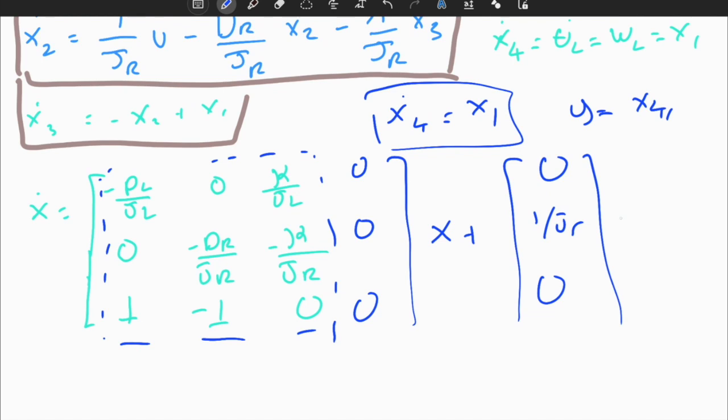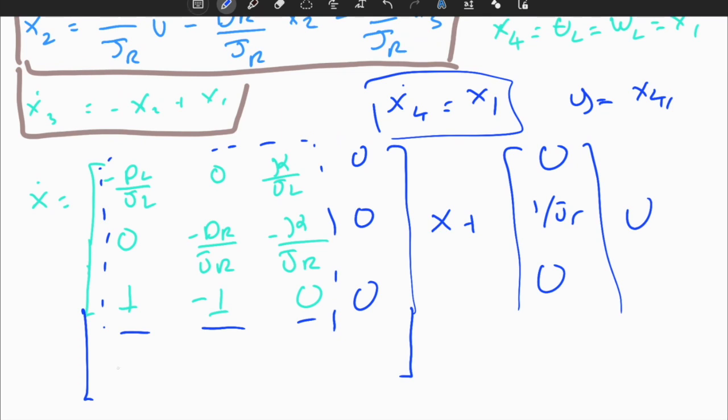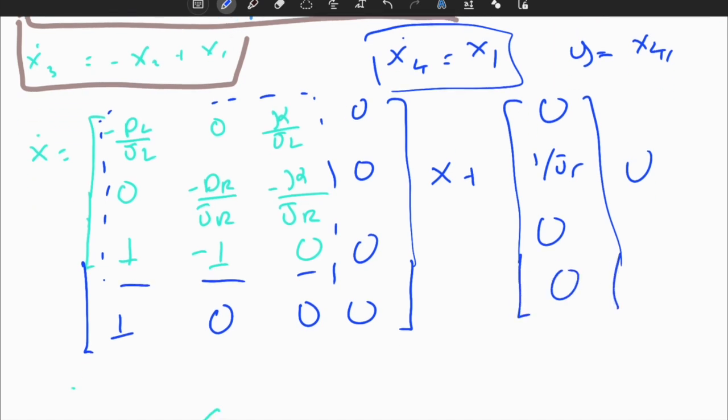And now the fourth new state equation. Okay, so I increase that. x4 dot depends on x1, but only that. 0, 0, 0. And it doesn't depend on input, so it's equal to 0. As you can see, I changed my output, which increased the order of the system because my new output is the integral of another state variable. It can obviously increase the order of the system for some examples, not always. But at least what I did is I used an important portion of the previous solution to finalize my new system, because the system is not changing. Only the definition of output is changing. Of course, I should use most of the part that I did in the previous part.